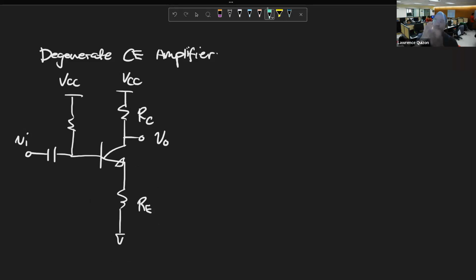Again, why do we do this? Well, to make the circuit more stable against changes in the transistor, which tends to happen all the time. For example, if your metal contact changes, or the connection gets worse on the breadboard. Even if you don't replace the transistor, you experience a lot of variations in the behavior of your transistor over the course of a lab class.